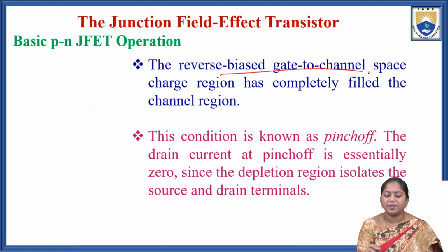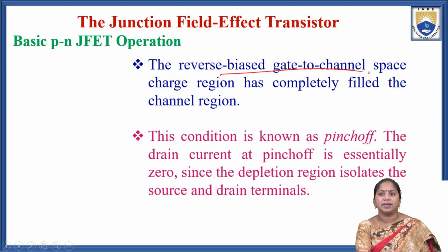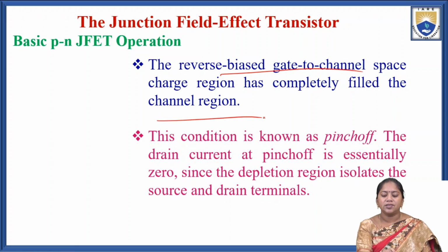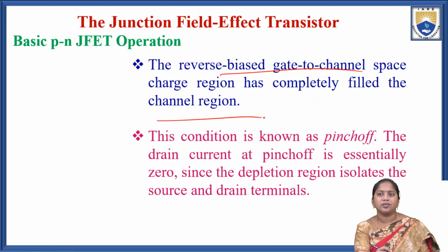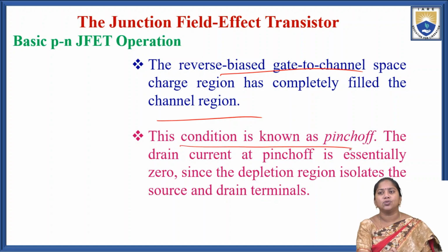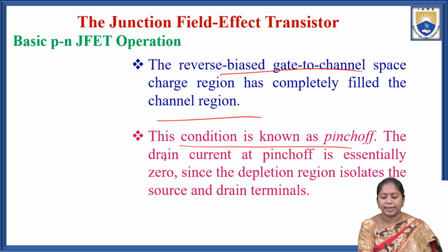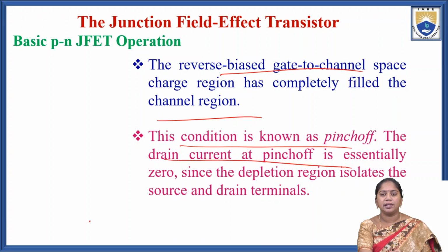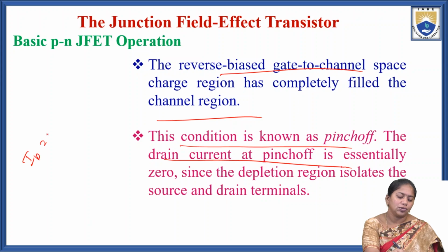So if you increase the reverse bias, the gate to channel space charge region completely fills the channel region. This condition is known as pinch off. The drain current at pinch off is essentially 0. ID equal to 0 at the pinch off voltage.